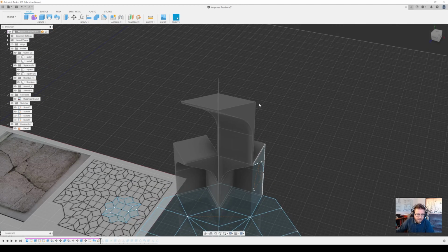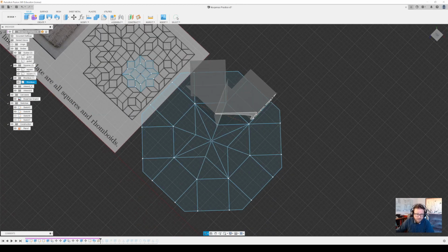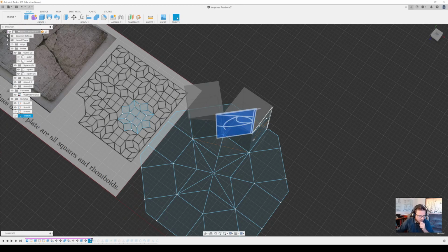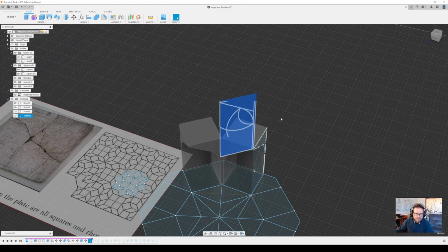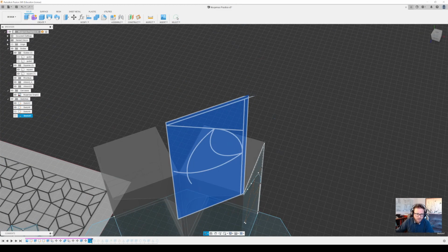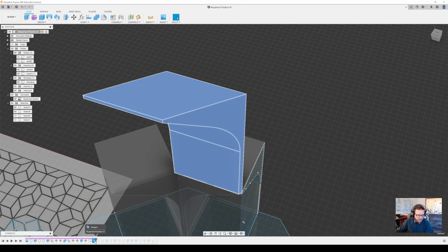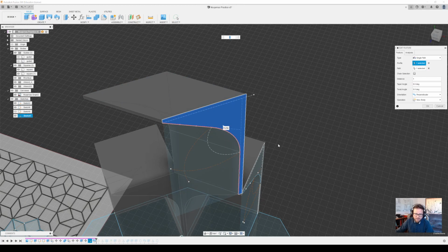So that anything that you've done on one side, and the other issue is when you create this, just to go back a little bit, I don't want to do what I did with the square, which is use the extrude command because it really is only going to work in parallel. What I want to do instead is use the sweep tool. The sweep tool, if I open this up, is a lot like that extrude tool.